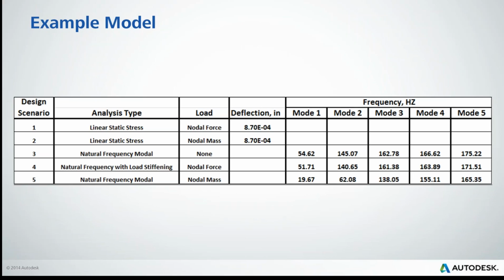So again, arguably you could do a natural frequency with load stiffening analysis and include the mass and gravity to represent that. Then yes, you get both the mass effects and the effect of the small amount of force included there. But to Marwan's point earlier, that change due to including the force is so minor compared to the mass that you almost don't care most of the time. That's true.